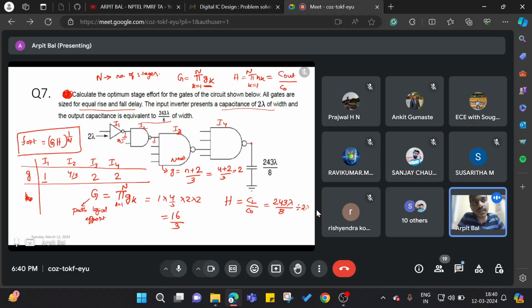We use several layers of simplification to ease our calculation for understanding the drive strength or the optimum number of gates that we need to use. So this is another simplification that has been used. Yes, whatever point you mentioned is correct. This inverter will also have its own parasitics that will act as a load, but for simplification purposes we are not going to consider that.